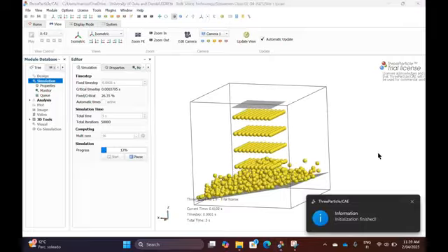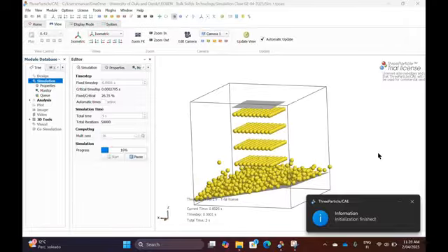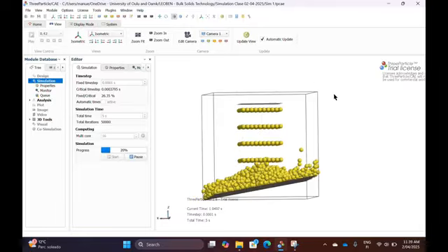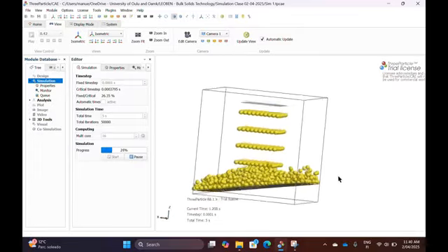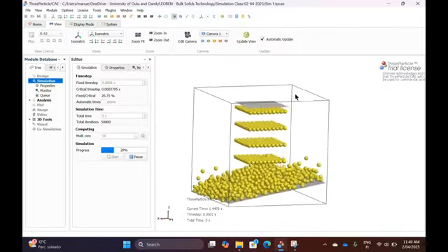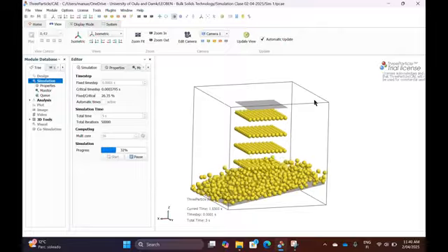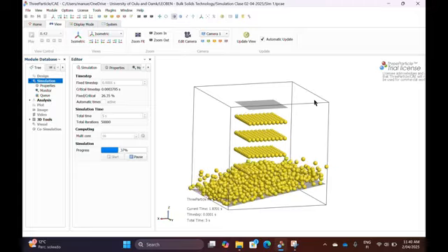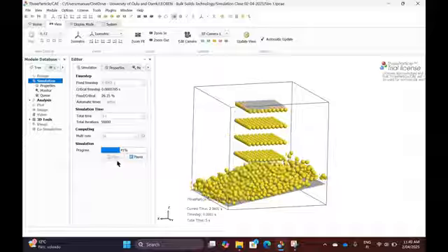So we are already at second 1. Particles that leave the system are deleted, you can see that here. And the particles are more or less thrown here on the plate. Now, with the pause, I can also change the time step at any time I want. I already said that, right? I can change anything at any second. Stop now. And now I will show you what it means if the time step is critical. This would be a supercritical simulation. The time step is much too big. If anything like that occurs on your system, go back.